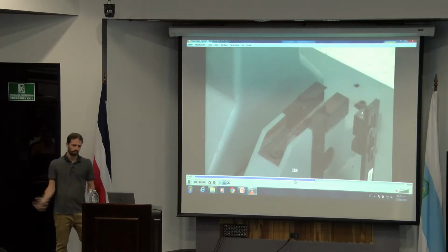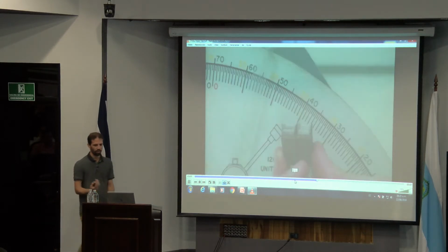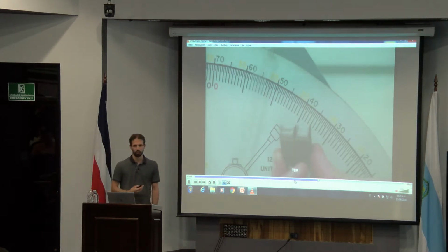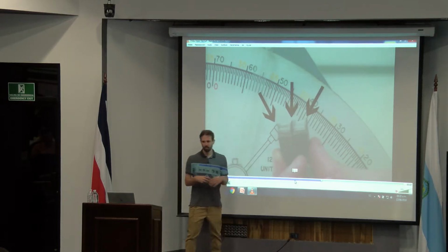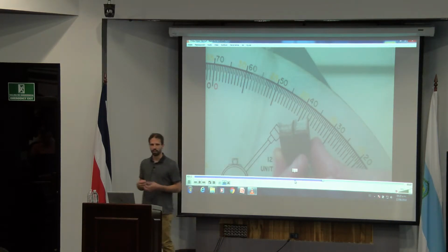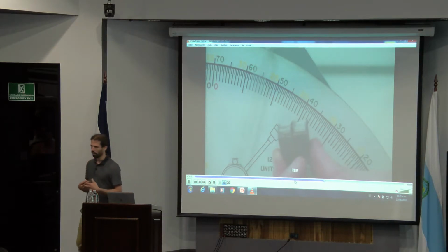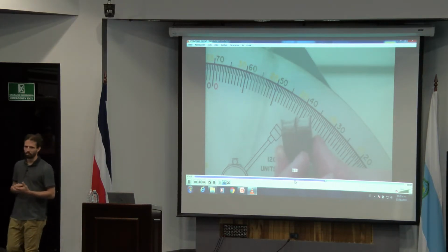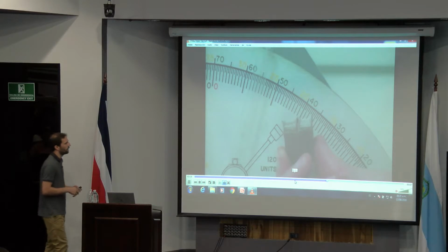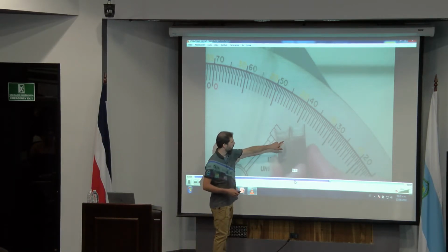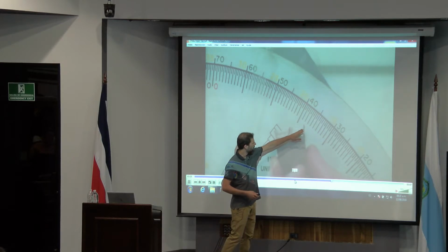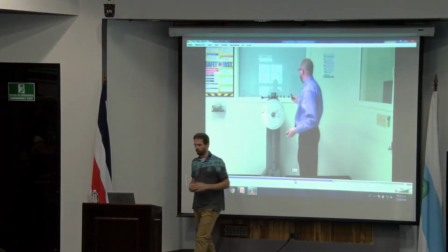And then cut through the specimen, and this is basically what you're doing in a Charpy test. So as you can see here, this is the specimen. In this case, it is quite ductile material, so it was a heat treatment material, as you said. And also due to this, you have here this small deformation, and also on the side some flanks.